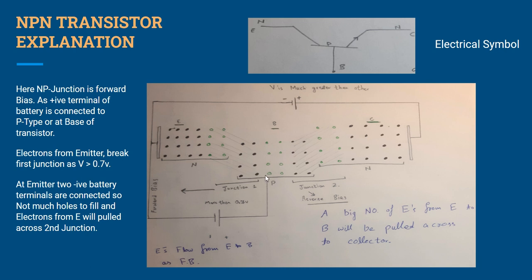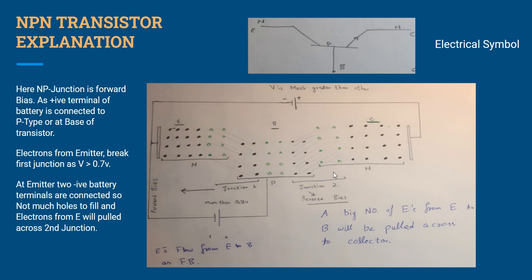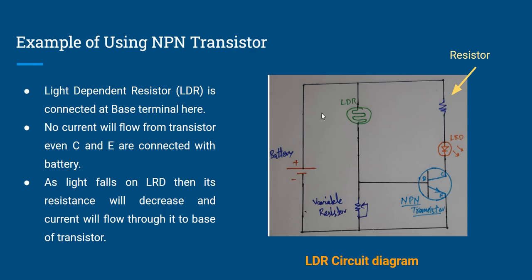That's why this direction is downward, and we are moving from collector to emitter. In this diagram you can also say the positive terminal goes here and it will flow like this. Yes, obviously in calculations we will go like this, but in understanding we are going like this. So don't mix these two things. That's why the electrons are flowing from emitter to collector. Right?